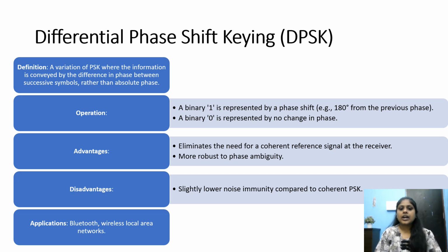Advantages: eliminates the need for a coherent reference signal at the receiver. Disadvantages: slightly lower noise immunity compared to coherent PSK. Applications: Bluetooth and wireless local area networks.